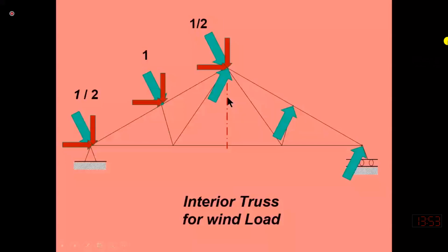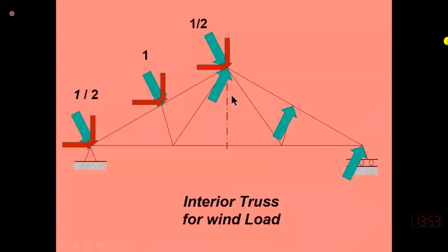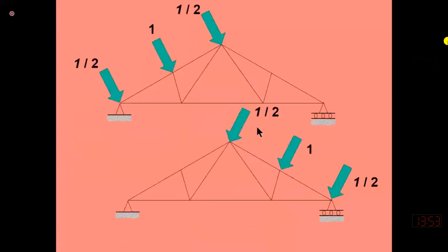If you multiply with -1 and add these forces, it will be equal to the resultant force. So you have already multiplied this wind load analysis with a negative. It means that the effect of the wind load analysis when you consider the wind load on the leeward side will be the same as if the force is acting on the upward side.